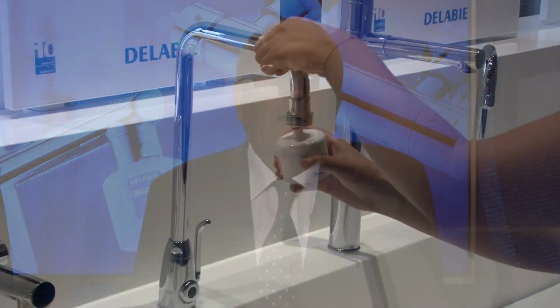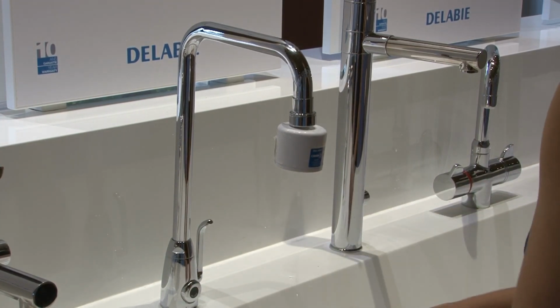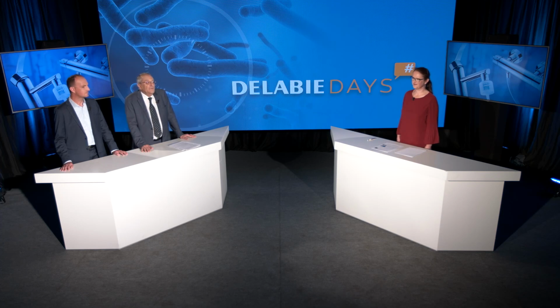To conclude, if a healthcare facility is unable to meet the requirements and cannot review its entire facility, then there is no other option than to use point-of-use filters. They are the only means of delivering bacteriologically controlled water, regardless of the setting. I will even go as far as to say that a 0.22 micron filter should be the standard solution for any installation and for sensitive areas in particular, and especially immunocompromised patients. They retain all microorganisms, including Legionella and Pseudomonas, given the cut-off threshold for this kind of filtration.